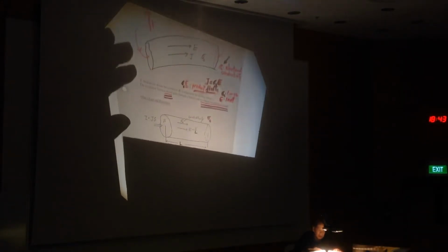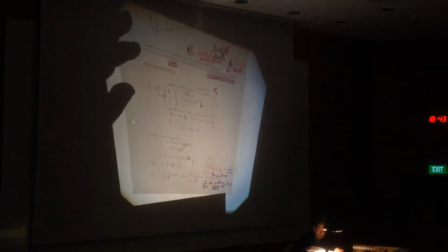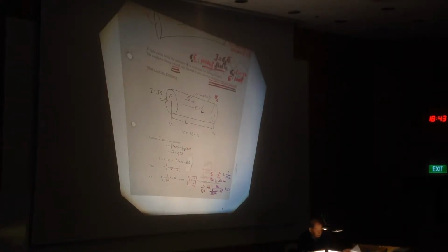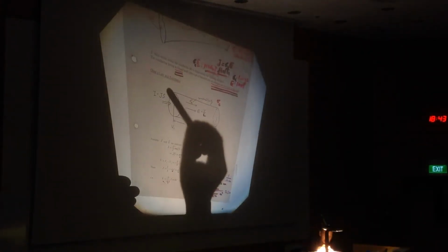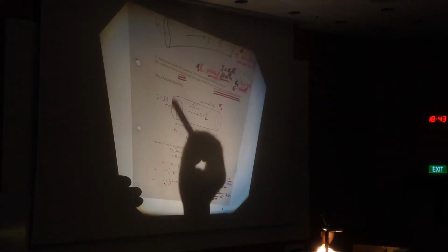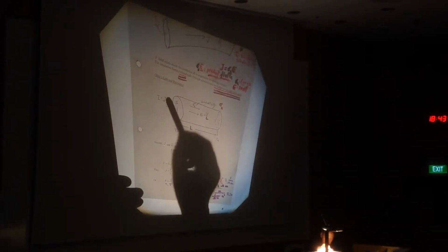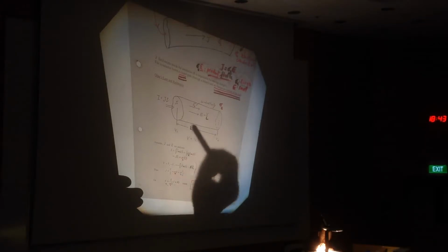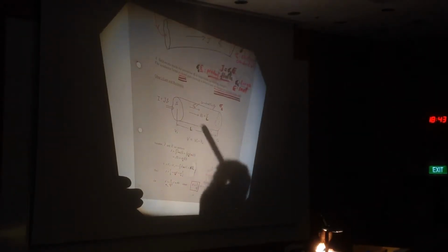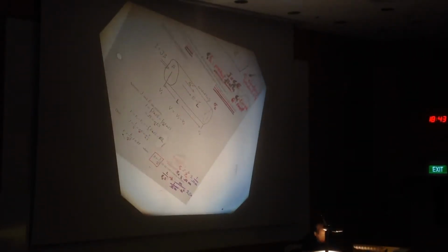So for a conductor with DC current flowing, and the electrostatic field, the fields are the same. So at the bottom here, a simple derivation of Ohm's law. This is surface S, current flowing at 90 degrees, so J is at S. Ampere per meter squared times meter squared equals amperes. So this length is L, not inductance, length L.